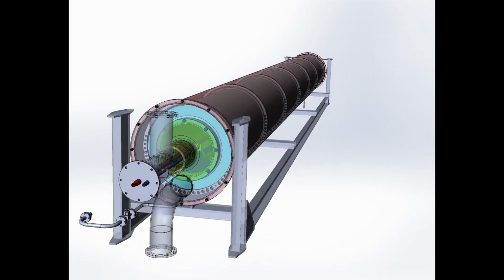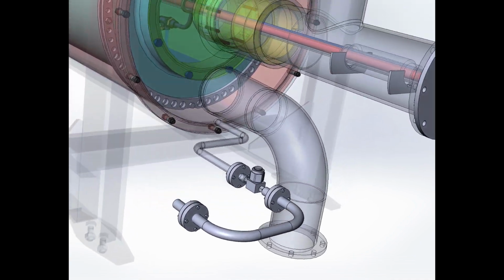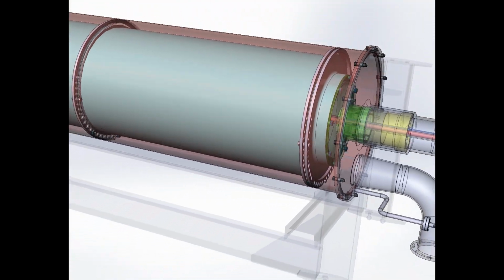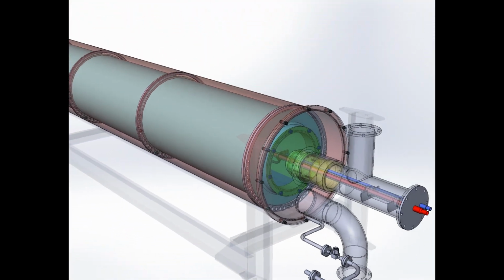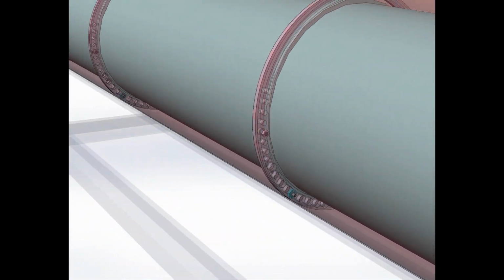When heating steam is supplied to the housing, it must pass freely along its entire length through the ring supports in the channel between the housing and the drum, for which holes are made in the expanded part of the ring supports. At the very bottom of the rings there is a cutout for condensate to drain to the discharge point from the housing.